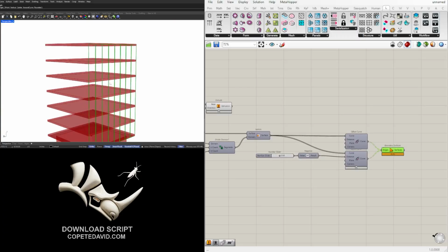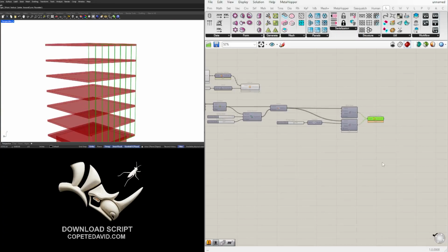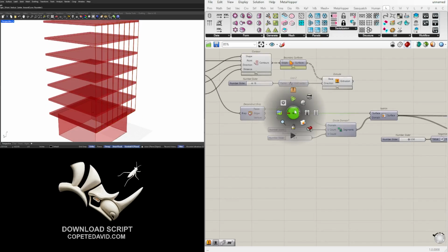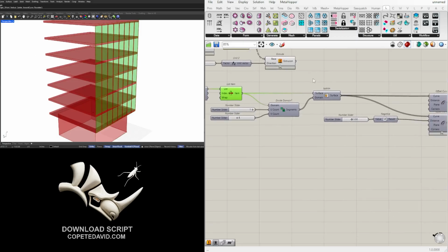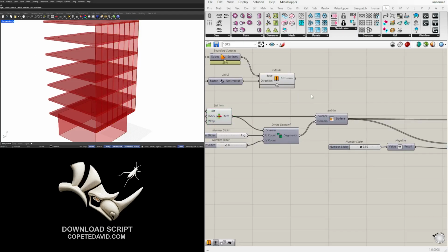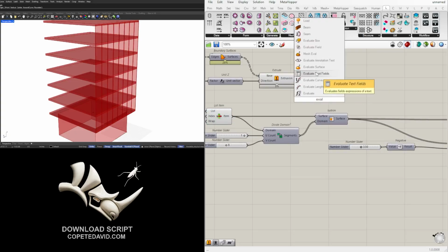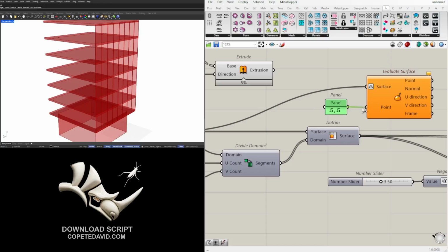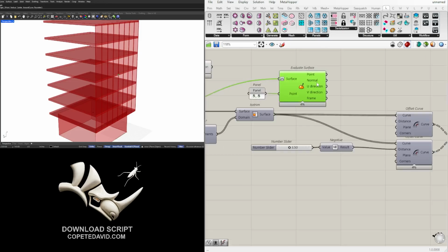And now we can use this to extrude it. Now to extrude it, we do want to use the normal from this surface. What that means is perpendicular to the surface. So to do that, we can use Evaluate Surface, reparameterize it, and then use the point as the middle. So to create a point, we'll do 0.5 comma 0.5. So that's 2 x and y values. And since it's at half and half, it will put it right in the middle. And we have a normal here.